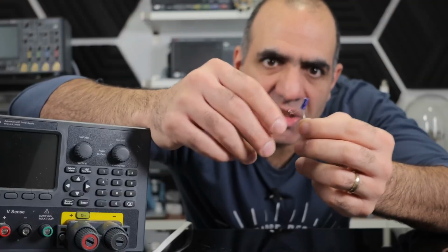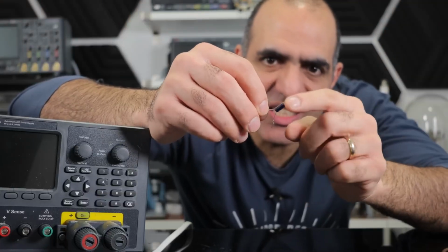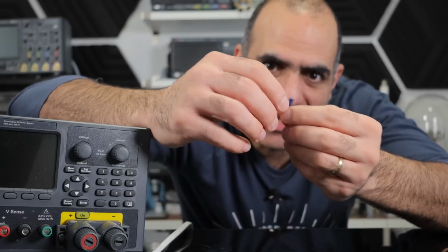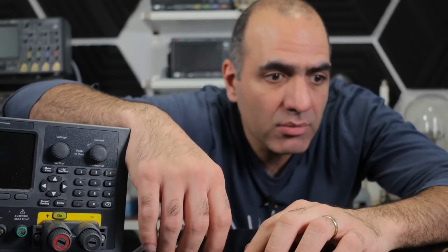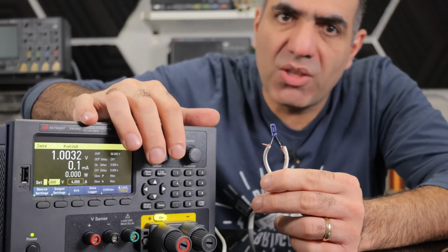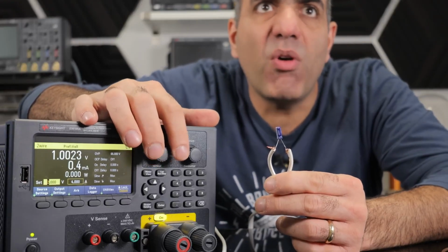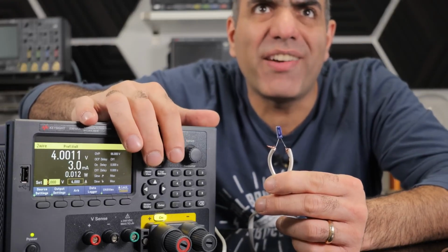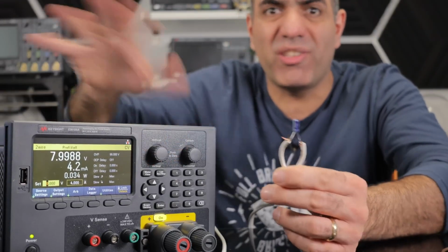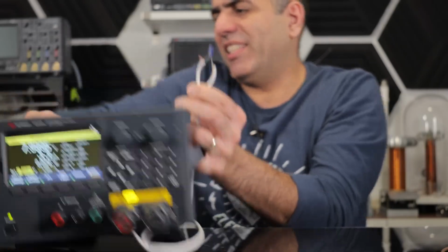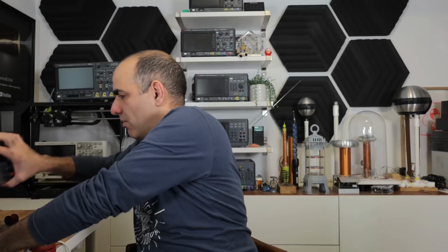I guess it's like a pressure cooker. The dielectric gel in these electrolytic capacitors boils and the pressure builds up until it blows up. I just want to half break a capacitor. I guess I have to let it cook slowly, so I just give it enough voltage for a little bit of current so that it doesn't blow right away, and I just put it on the side and let it get damaged over time.